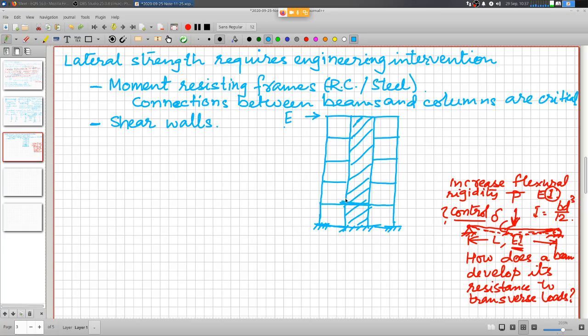So sometimes you will find that the shear wall is only erected from the first floor or second floor level, and this is all left clear, or even the columns, maybe the columns are there, so this causes another problem. If this happens, then this causes what is known as a soft story.